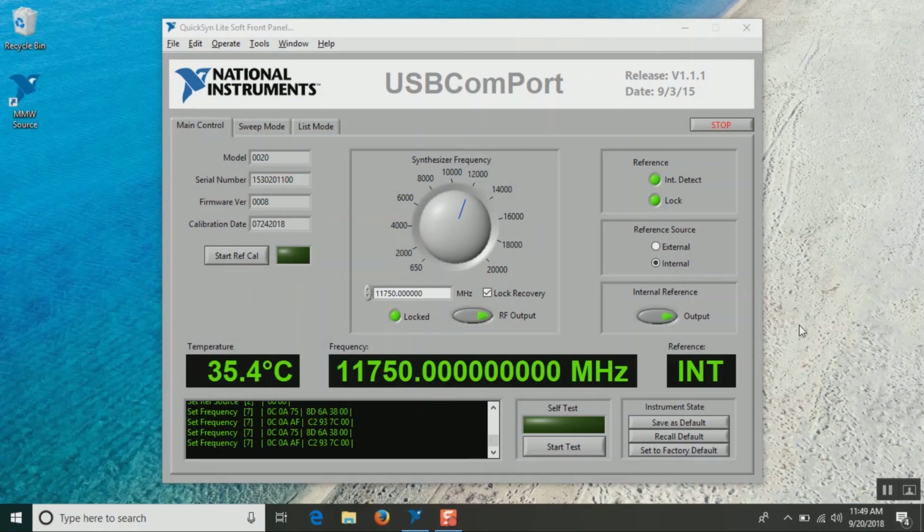Default power on settings. Currently by default, as we have seen, the unit powers to 94 GHz on power up. If you want, you can change the default state of the source on power on to any other frequency between 92 to 95 GHz. For example, let's change the default power on state to 95 GHz.